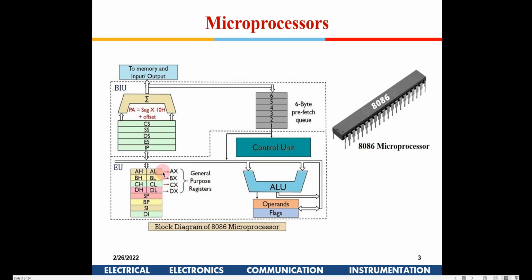And it requires a few internal registers. So now also the output of the ALU, it depends on architecture to architecture. In most cases the output will be one of the inputs only. So once you do A plus B, the result will be stored in A itself. So that is why it is known as accumulator. In some other architectures of microprocessor, you do A plus B, result will be stored in a third register. It could be C or something like that. So those kind of things we are going to see today, and obviously there will be some flags,